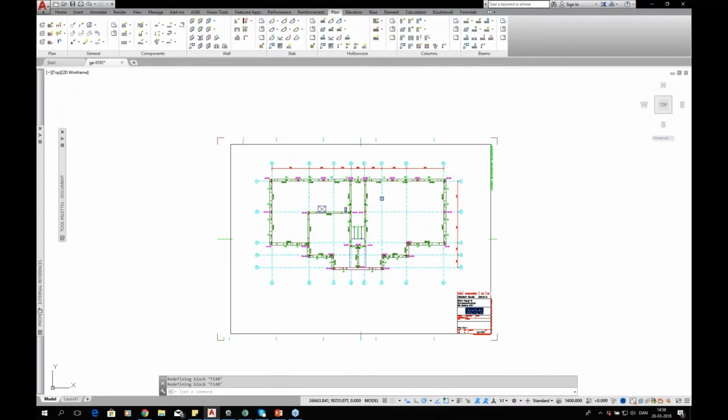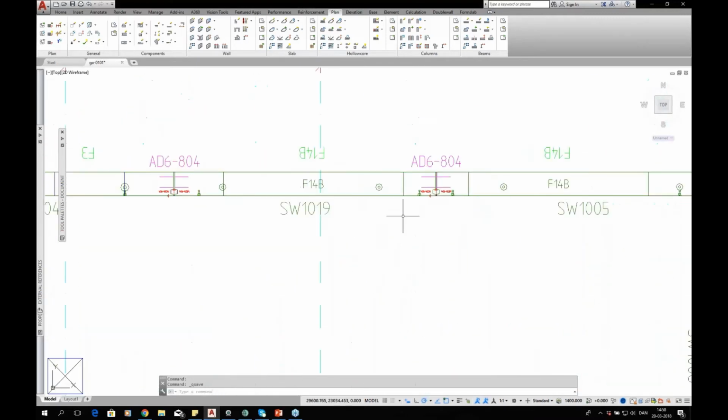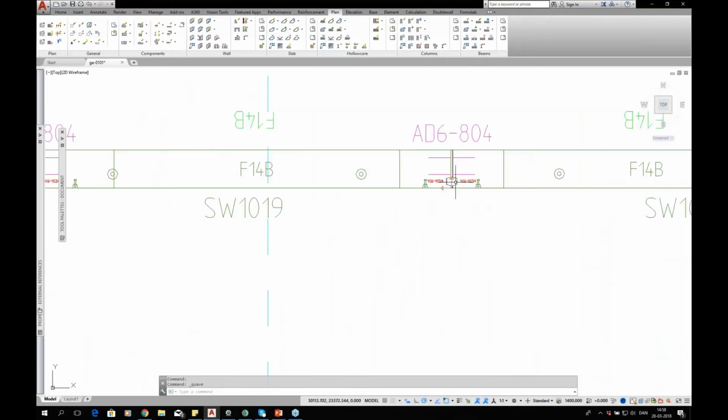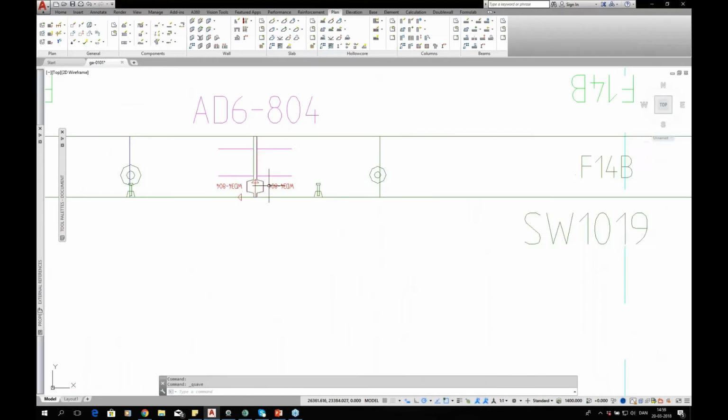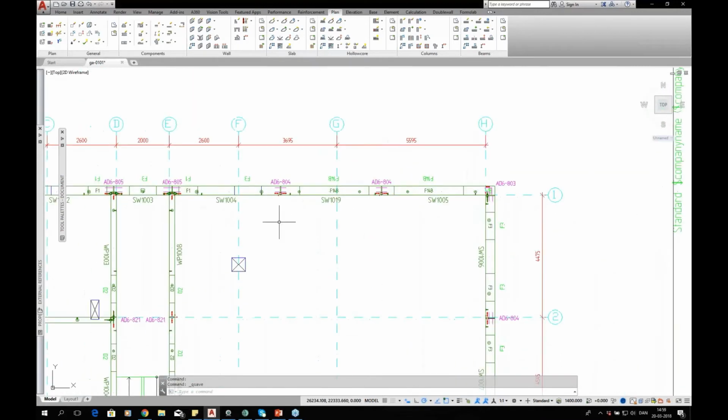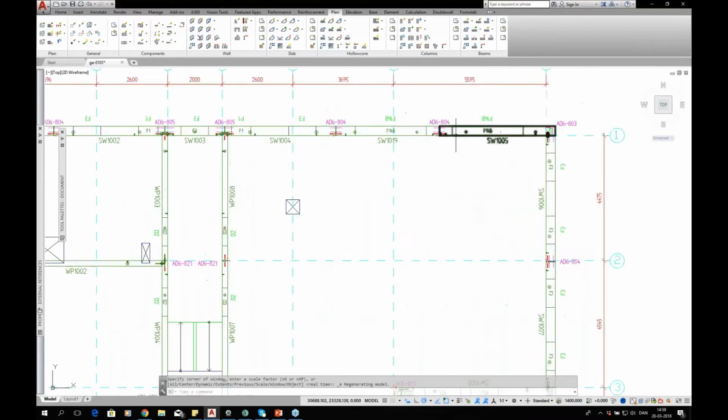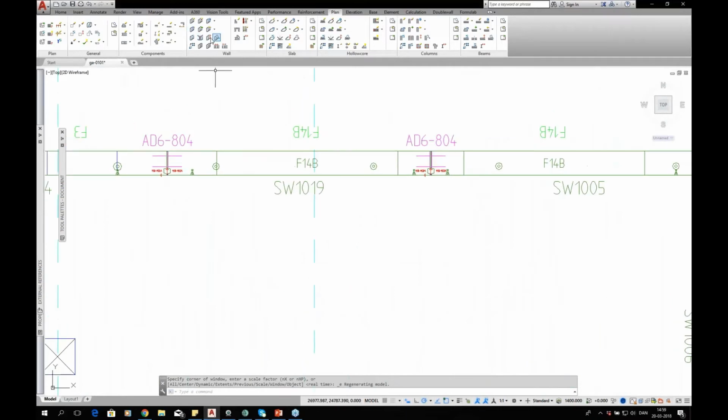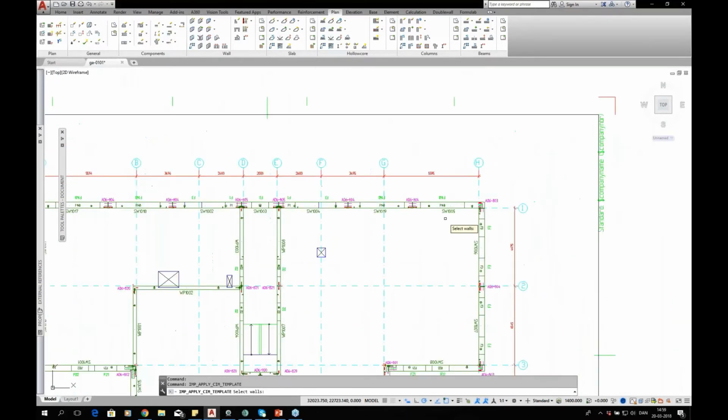And after finishing up the walls and sandwich panels, I want to add some hollow cores, and I want to add some double T-slabs as well. Before doing that, some of you might have noticed that I didn't put wire loops into the straight connections here. That was on purpose, because I want to show you a different way of doing these, which is called cast-in material templates.